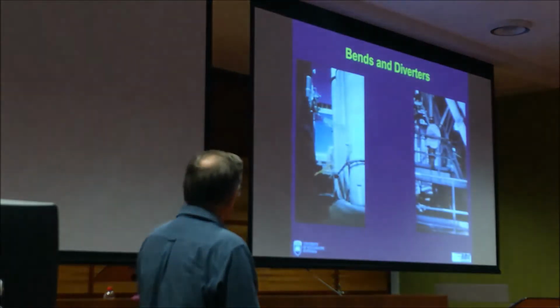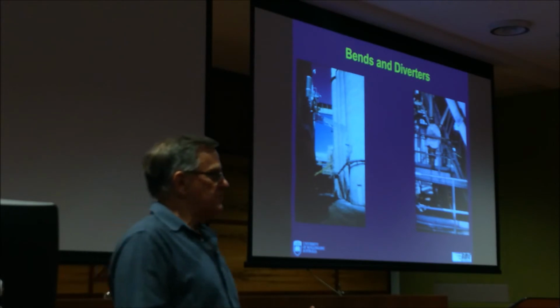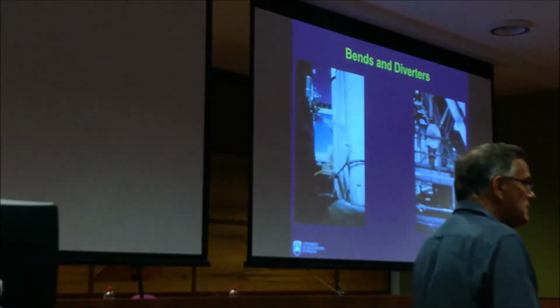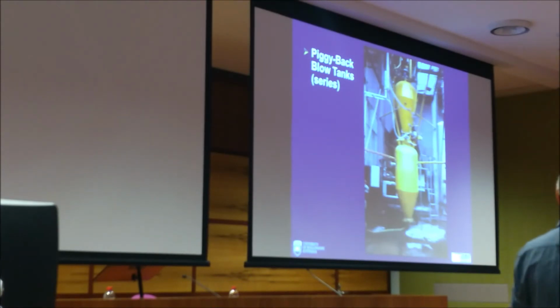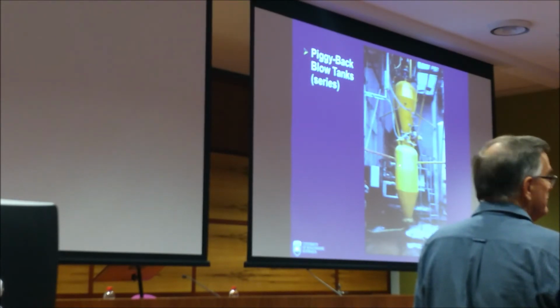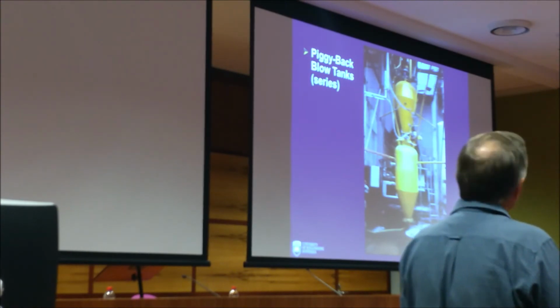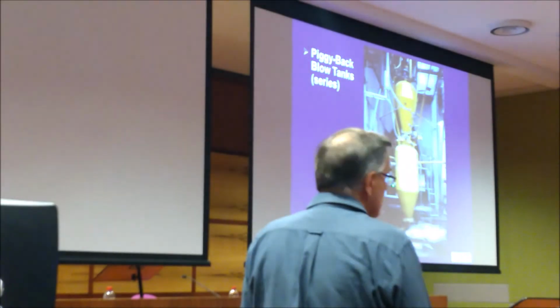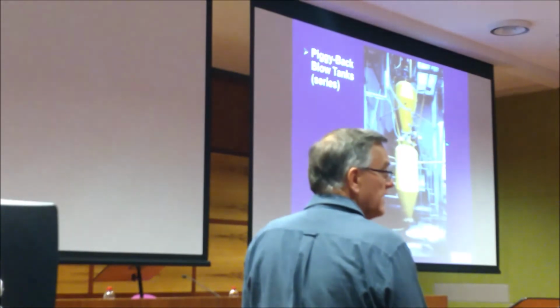Alright, just quickly before we go for the break, a very quick slide. Oh, sorry, question there. Yes, sir. When you're in the piggyback system, so when you're repressurizing and clearing out the material, is it 100% clear or some of it less? Yeah, so all the material here drops down under gravity. So we've got the pressure balanced here across the valve. So when we open that, the powder drops down under gravity. Right? And then once that has fully discharged into the bottom vessel, we then close that valve again.